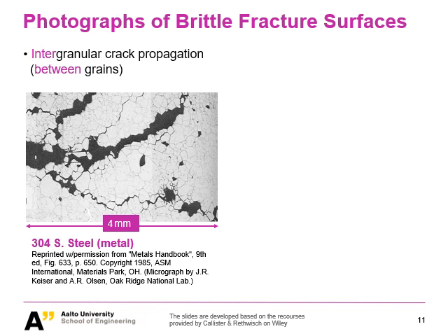We have seen brittle fracture from large components like pipes to the smaller ones of our tensile tests. Now we want to see how brittle fracture looks when we look at the microstructure. Here I'm showing you one micrograph of brittle fracture in stainless steel 304, a common one used in cookware.